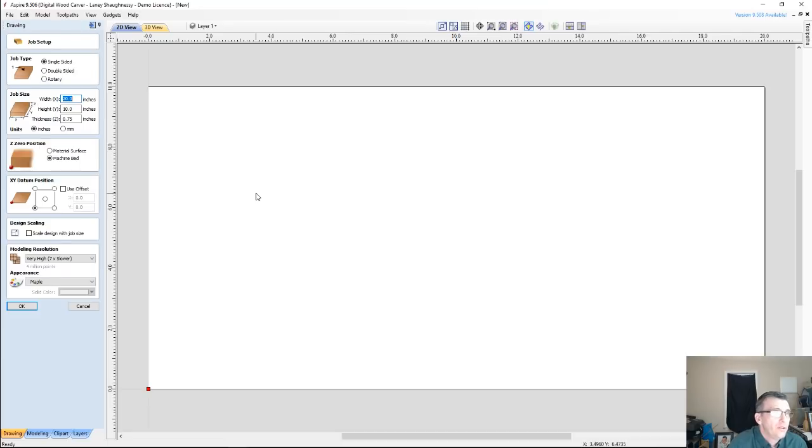With regards to the rotary option that's now available in Vectric 9.5, the rotary has the ability to work with G93, which is a time insertion. Basically, it keeps a consistent feed rate for the design versus slowing down and speeding up, which allows for a more consistent and clean cut.